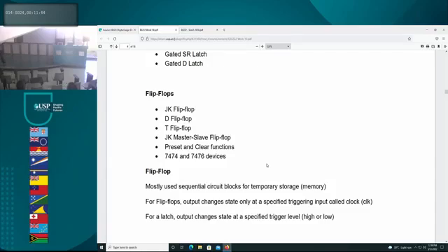Now the D flip-flop is the 7474, also known as the 74LS74. As you go through this course, you will become familiar with many different chips. For example, what is the 74LS00? By now you should have used it so many times. It's a NAND gate. Then you have 74LS02, 74LS04, 06, 08. 7447 is the BCD to 7-segment display.